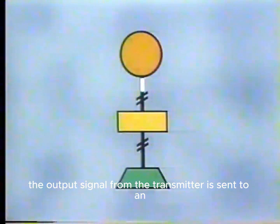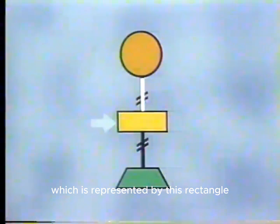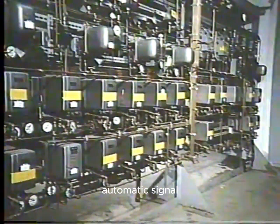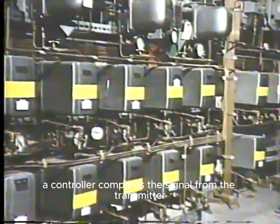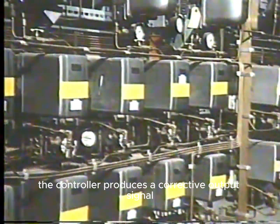The output signal from the transmitter is sent to an automatic signal processing instrument, which is represented by this rectangle. In pneumatic control systems, automatic signal processing is usually accomplished by a controller. A controller compares the signal from the transmitter to set point. If necessary, the controller produces a corrective output signal.